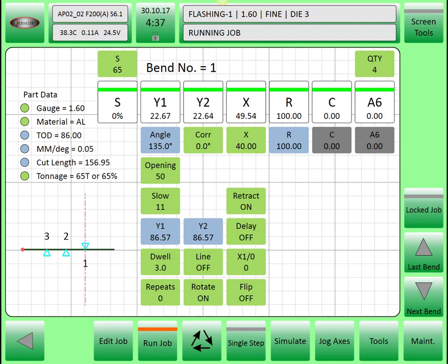For example, an emergency stop will look like this, with the movement axis inhibited and flagged in amber, and emergency stop being flagged in the main display. An X over travel limit switch firing would look like this, where it is shown that the x-axis has moved too far forward and the x-axis is being limited and inhibited until that error is cleared.